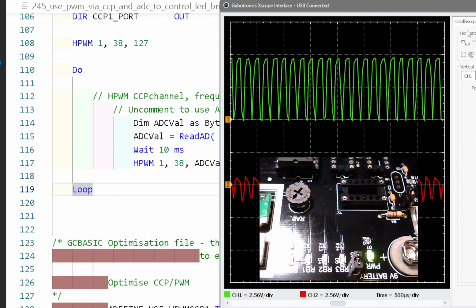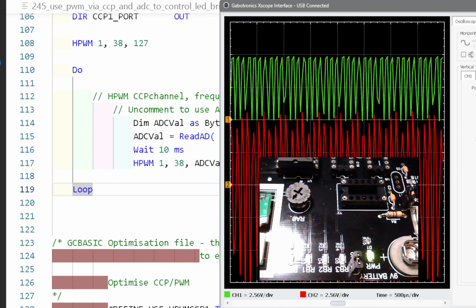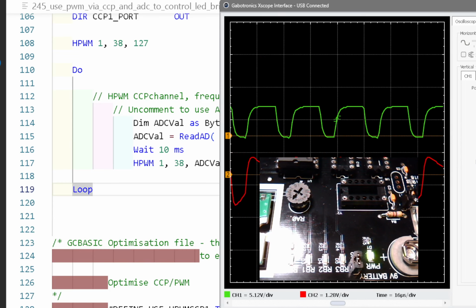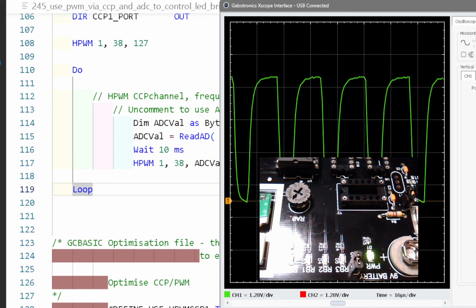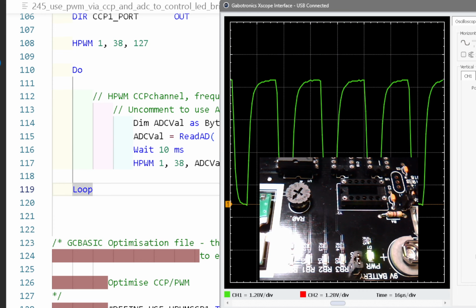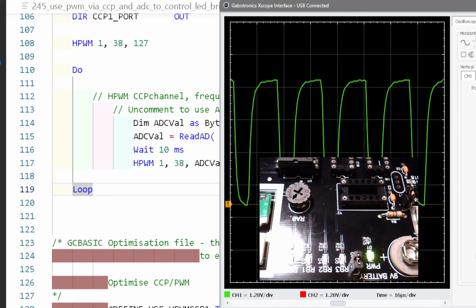Good. The oscilloscope's got 2 channels on it, look. Auto. Oh, look, I should have done that to start with. Trace, turn the trace off. Turn up the gain. Oh, it's not much better, is it really? Probably the cable I've got, the way I've got it set up here. It's picking up some noise, etc. I've also got an LED I can see stuck on there.